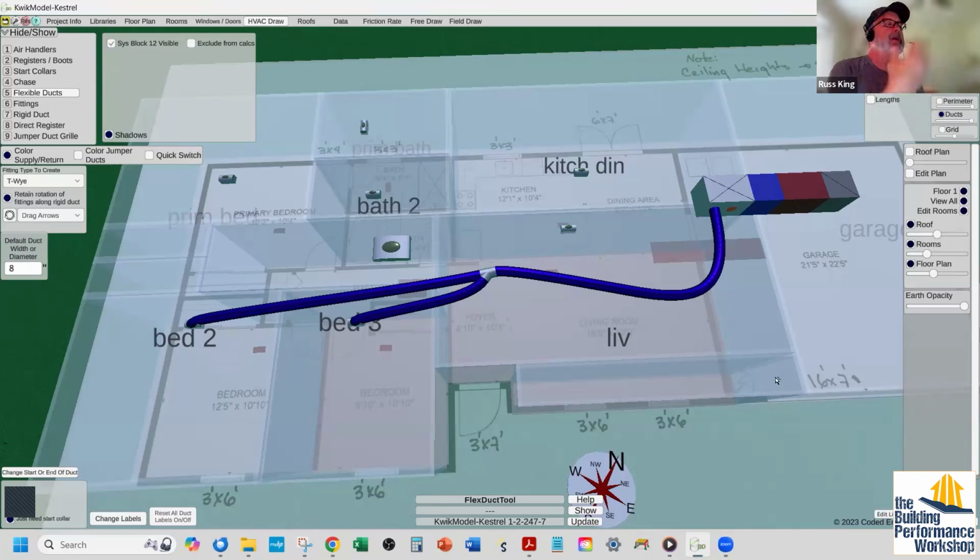One of the big complaints against flex duct is its performance, and it's the same performance as one size smaller sheet metal. In terms of airflow, it's very forgiving. When you make an elbow with sheet metal, you make a hard elbow, but when you make an elbow with flex, you can have a gradual elbow with virtually no pressure drop whatsoever. The one thing I will grant you that sheet metal is superior on is rodents.